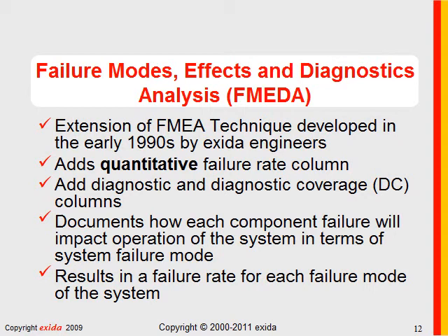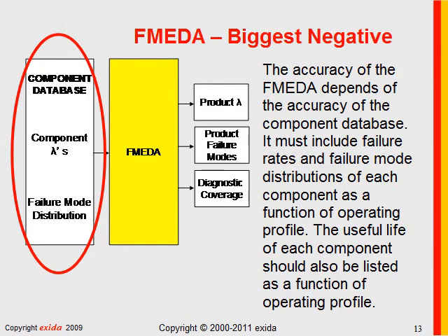If one were to add a quantitative failure rate column and diagnostic coverage columns, the FMEA could be extended into a much more detailed and useful technique for determining failure rate prediction models. And that's where we're going with this.